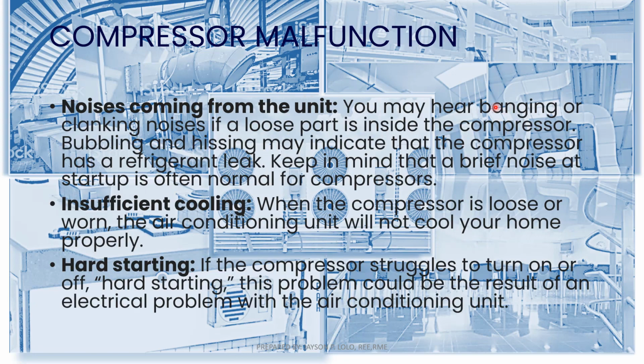Compressor malfunction. We have the three noises coming from the unit. You may hear banging or clanking noises if a loose part is inside the compressor. The compressor has many moving parts, and it is easily susceptible to breaks. So if the compressor malfunctions for any reason, the result could be noises coming from the unit, insufficient cooling, or